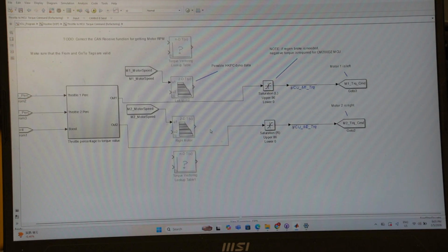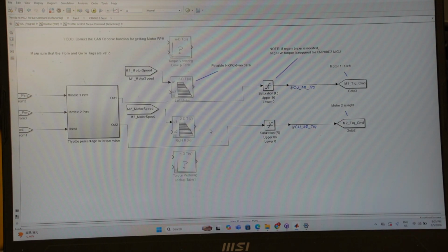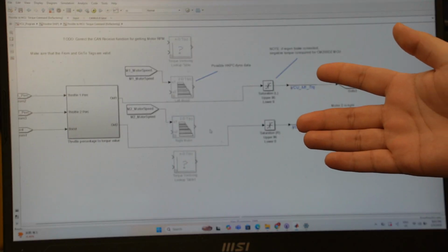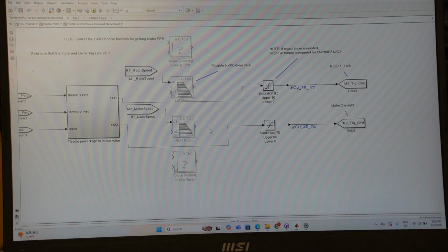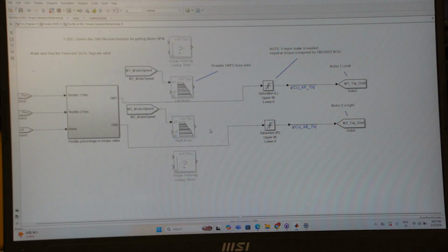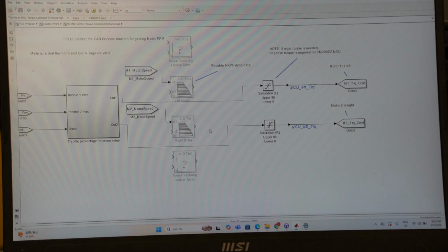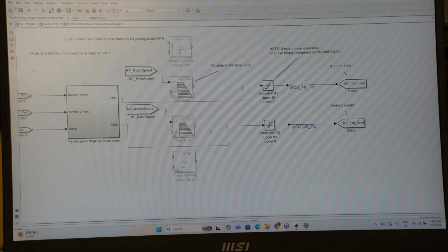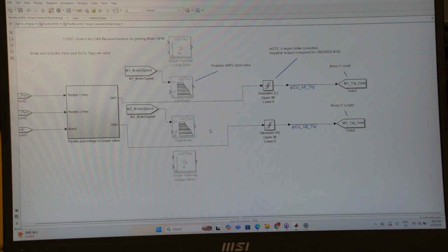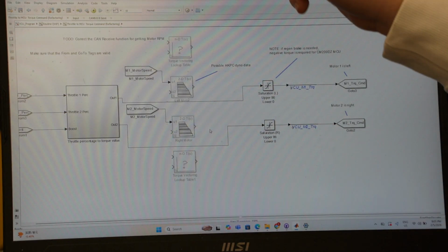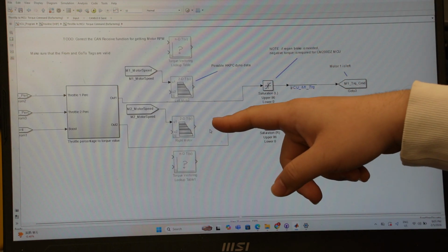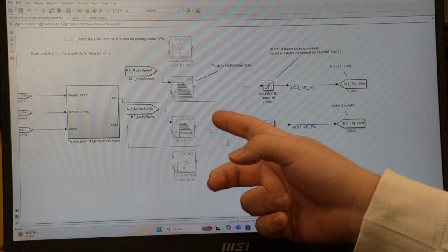So once you guys have the RPM sensor back, you can try to utilize this RPM sensor and also the lookup table. But there is no guarantee this data will function properly because we have changed the inverter. We are using a different inverter from what they used when they did the dyno testing at HKPC.